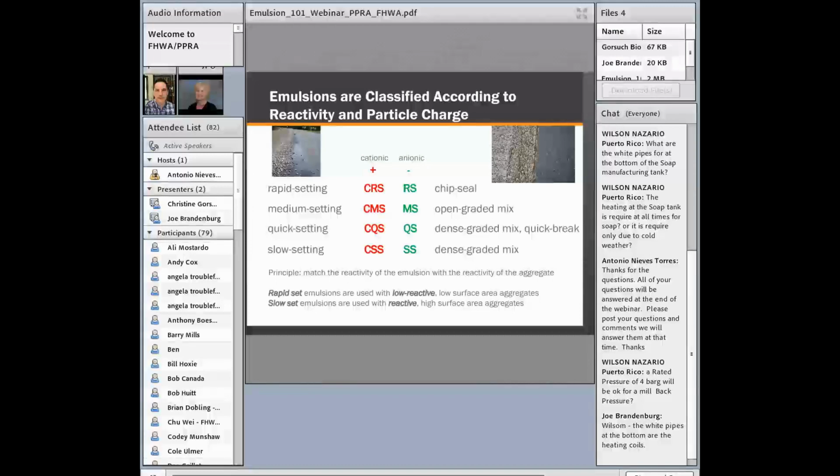For example, with a driveway sealer formulation that has a lot of dense material and fillers, we want a really slow and stable emulsion so that we can make that mixture and store it before we apply it, so we don't want it to break.